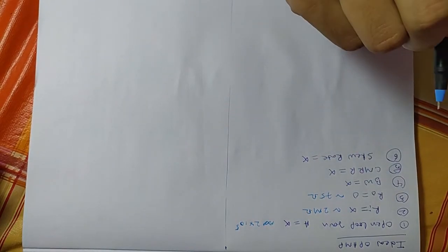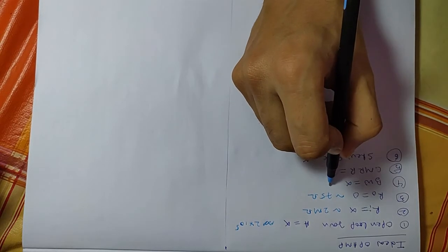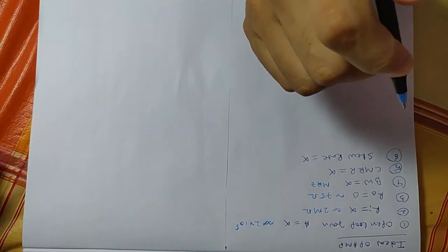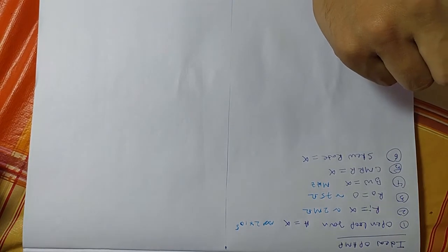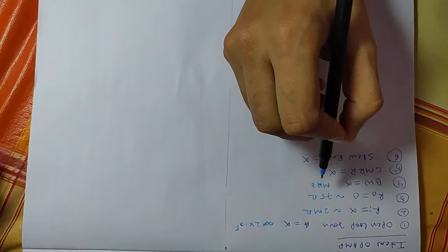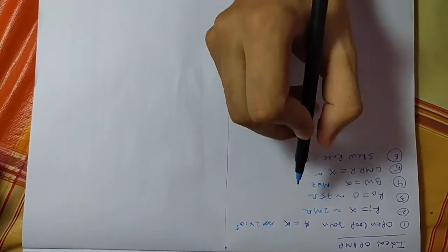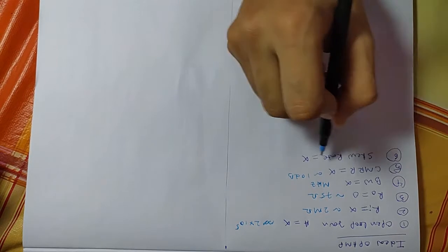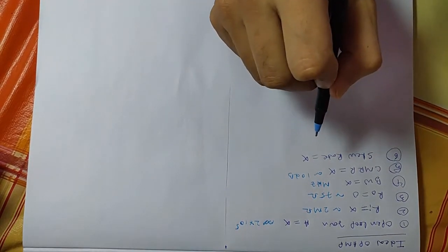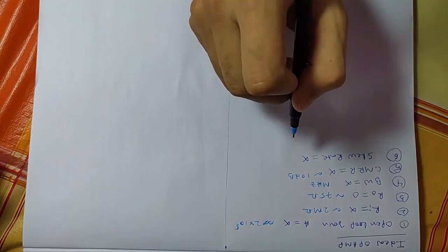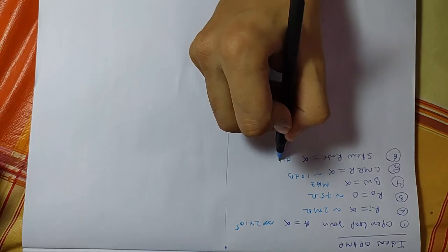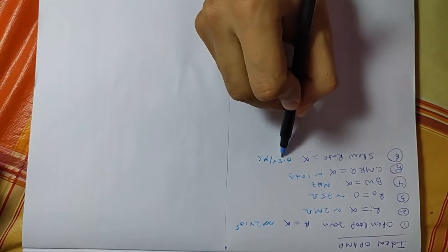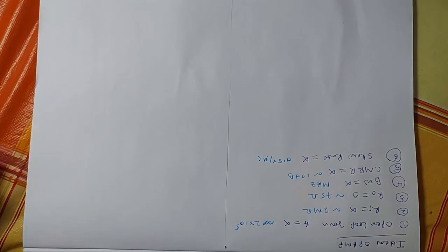Bandwidth is not infinite, but you can achieve bandwidth maybe up to order of megahertz. So you can amplify signals up to megahertz, and it depends on the vendor company which fabricates the op-amps. Slew rate infinite is not possible. Sorry, CMRR would be around 10 dB. And slew rate we measure in volt per microsecond, and typical op-amp has slew rate 0.5 volt per microsecond. That means in a microsecond output can change maximum 0.5 volt. So these are the ideal op-amp properties.